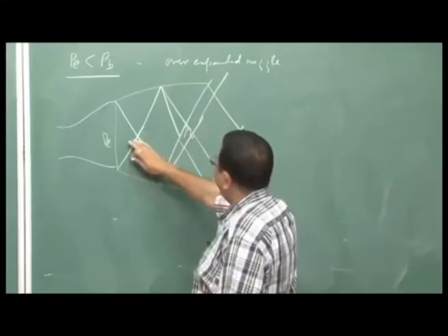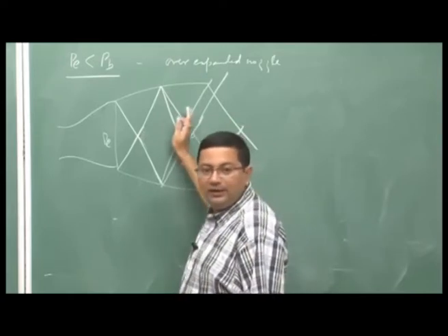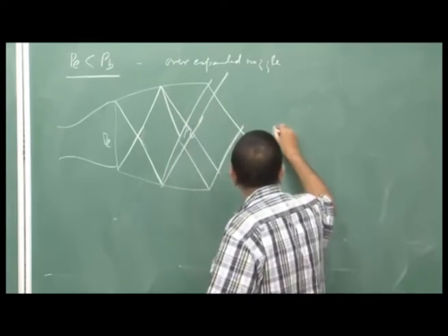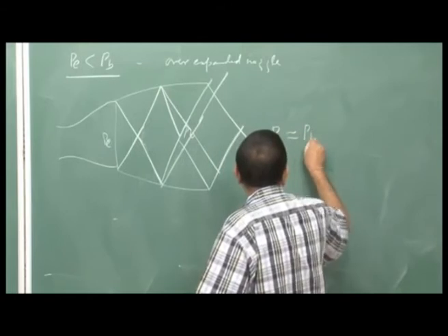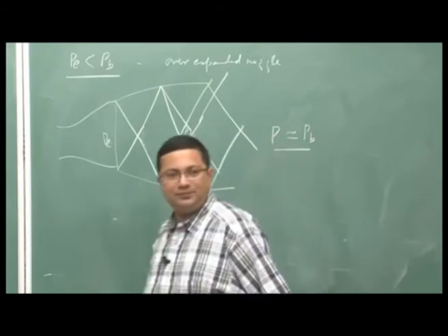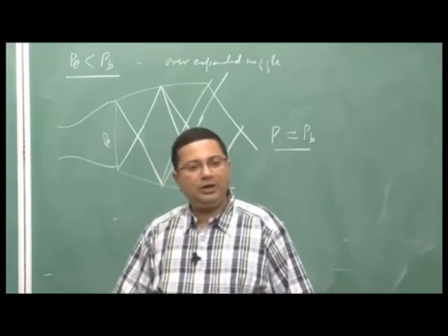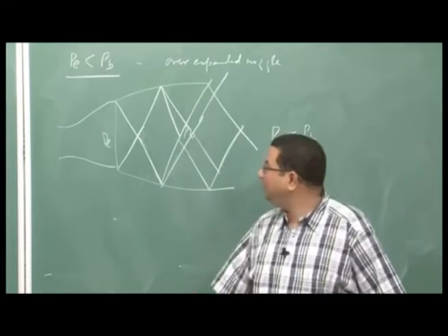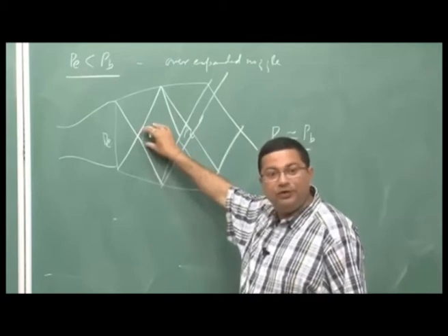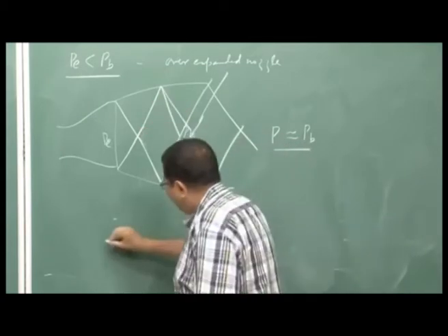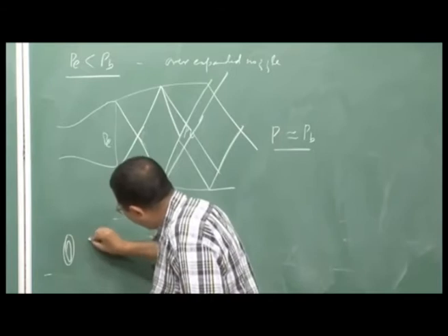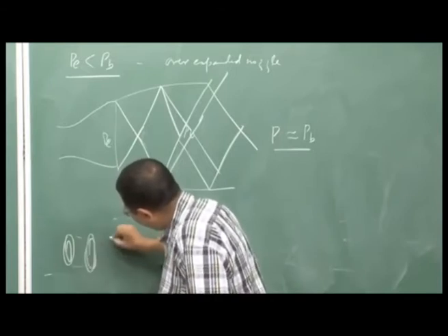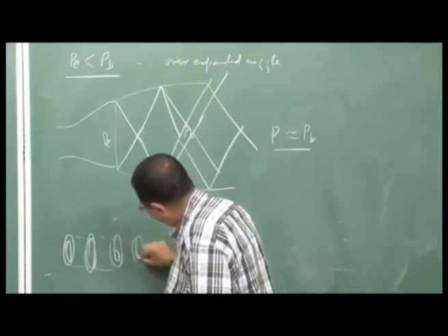Once again the pressure is going to gradually rise till we get a match, where the pressure is equal to Pb. Now, if you look at the plume of rockets operating particularly under over expansion, these are shock waves. So, the flow is slowing down, and the plume looks like this: bright regions, light regions, bright regions like this.